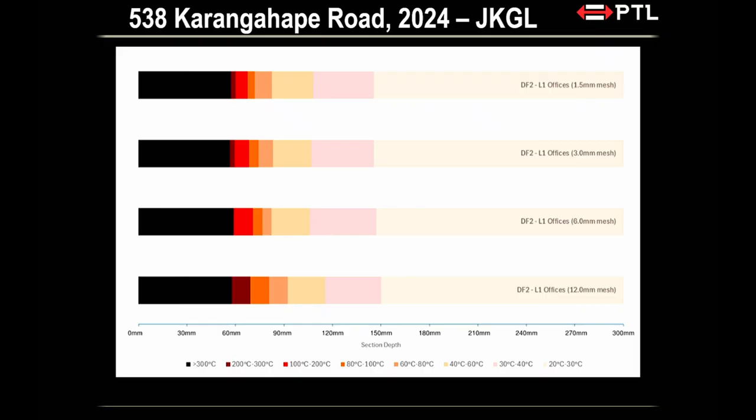So this is where your 100 degrees sits. So you have about 210. 210 multiplied by 2, you have 420 of section left. So is that enough for the loading during fire? All right? So if it is, then you've sized your column correctly. But if it's not, then maybe make it a bit fatter for me, please. Thank you.